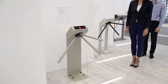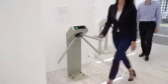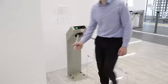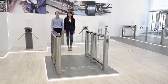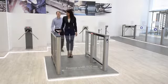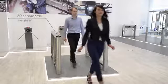For instance, a tripod has a passage width of 500 to 600 millimeters and throughput of 30 persons per minute. The speed gate has a passage width of 650 to 900 millimeters depending on the panel size and throughput of 60 persons per minute.